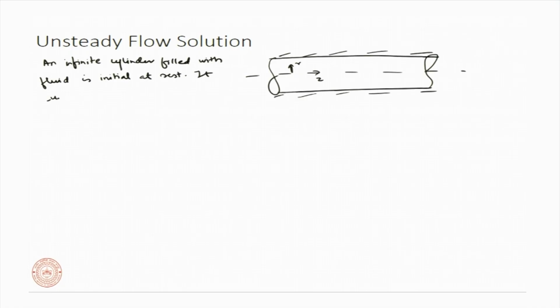It suddenly starts to move with a u velocity. Right. So, this will start to move with a u velocity all of a sudden. And initially, where the velocity was 0, initially at rest, the flow will try to catch up with this, and gradually you will come to the free stream velocity, that is u. Right. So, this is your transiency.